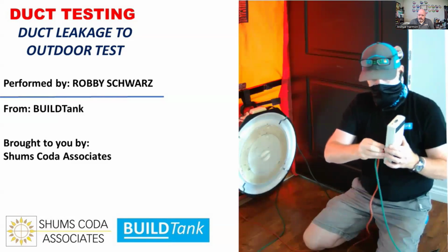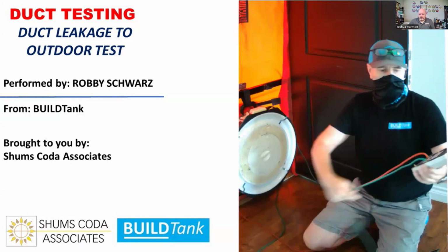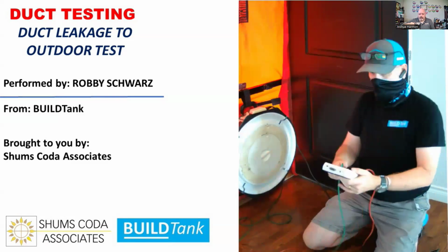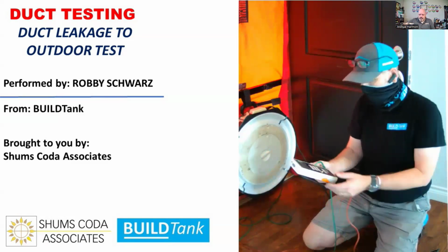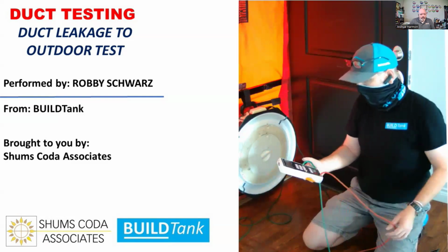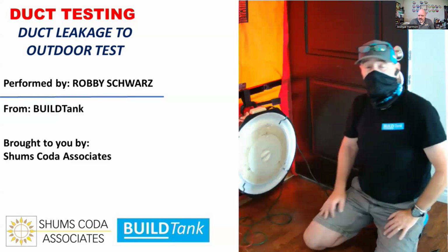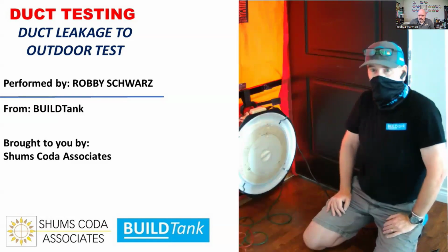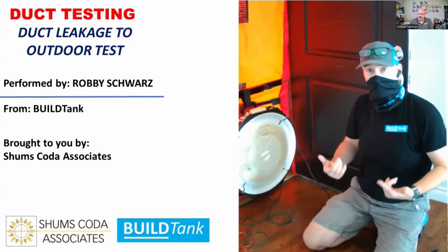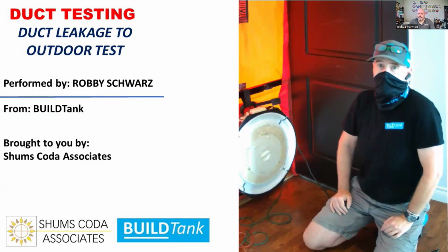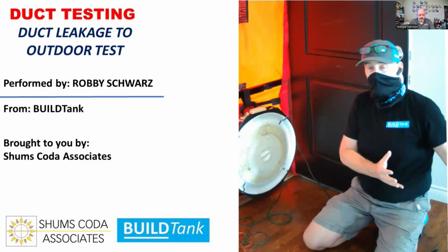And again, that fan pressure gets translated into a flow number. But when we do the blower door test, we're going to do an automated test. So the computer will do all the measurements for us after we've set it up properly. Before we do those tests, though, we're going to do a duct leakage to outside test. And the duct leakage to outside test needs a blower door and a duct tester running simultaneously in order to get that measurement. What we're doing is we're pressurizing the house with the blower door, and it works off the